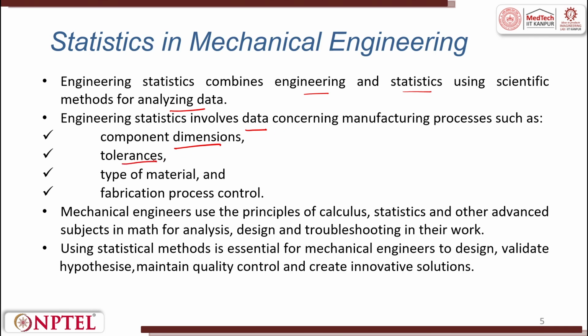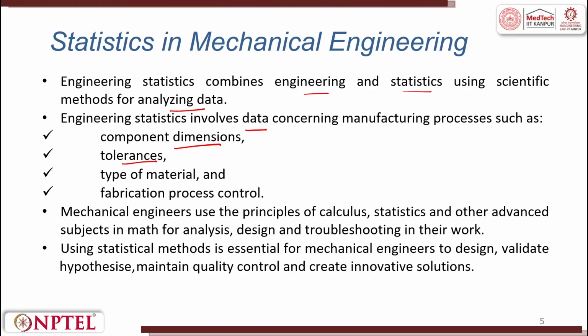Then come tolerances. Interference fit is a very tight fit. For example, a pen going into a pocket, that is a very loose fit. Putting the cap of the pen on, that is a little interference fit, that is why it gives a click sound. Then transition fit is between the interference fit and the clearance fit.